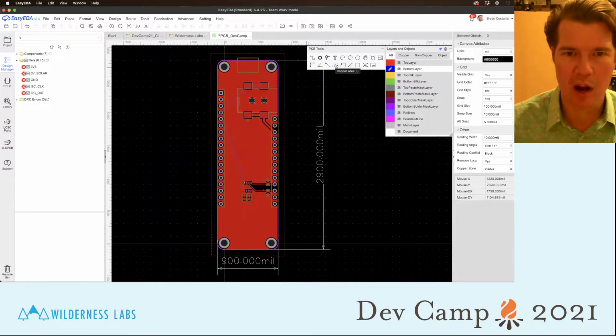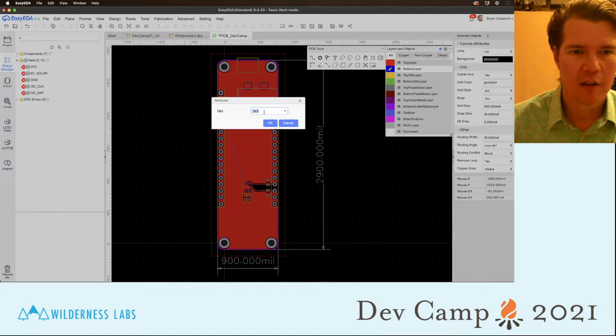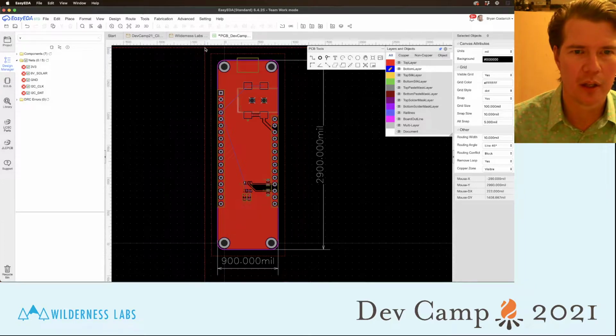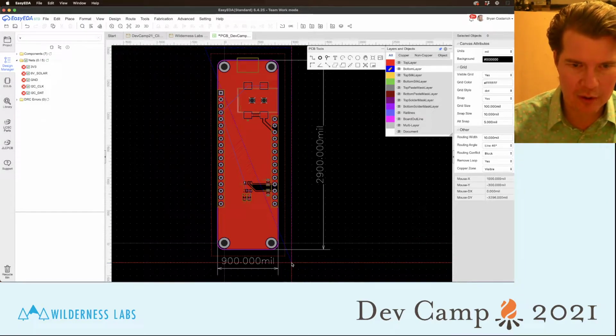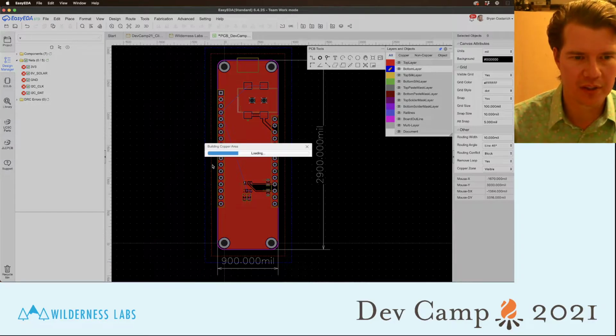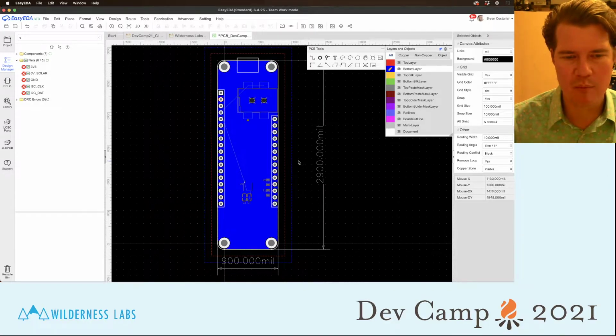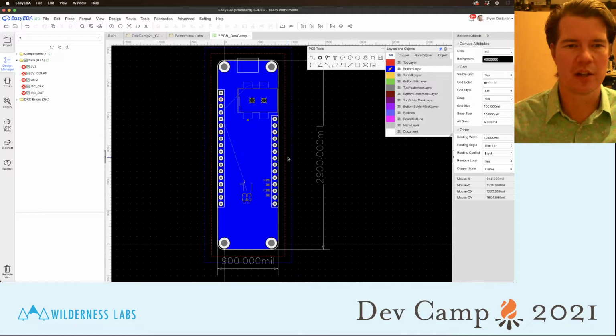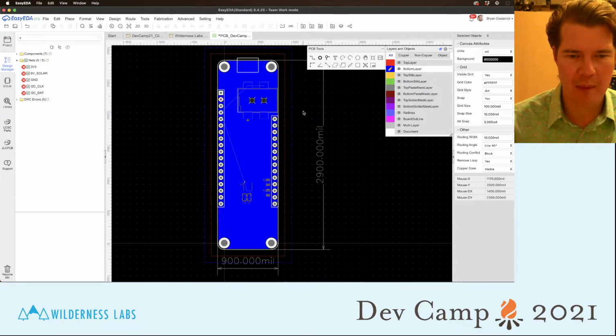And again, we're going to select E for the copper area tool, and hit ground, and then pour this outside of the other one so I can select it without competing with the selection of the other one. I'm starting from the top out, and I just make them concentric outlines. That makes it easier to know what's going on. So that's poured, and we're on the bottom layer. That's what we're looking at.